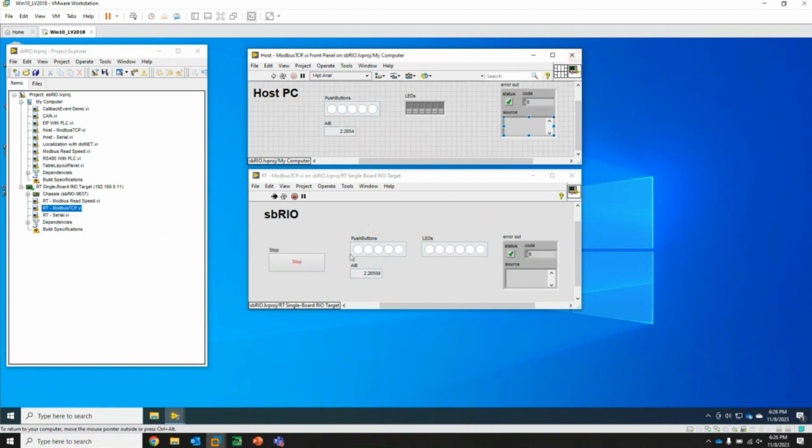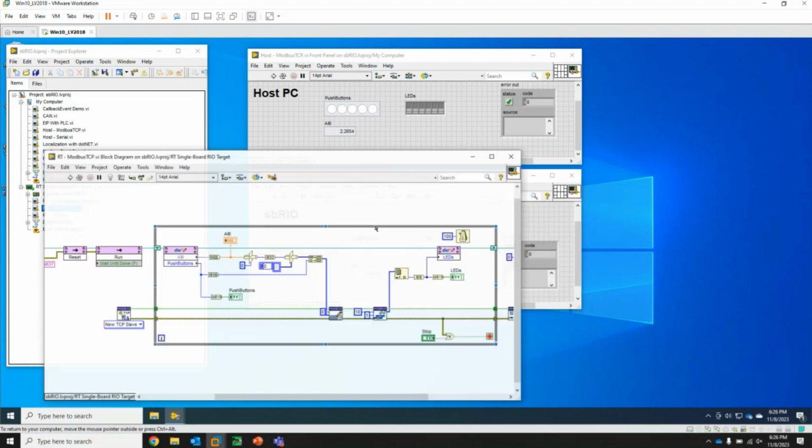I know this is for communicating with PLCs, but if you do have a simple real-time application and you're not trying to exchange too much, definitely use network streams or something else if you're pushing a whole bunch of data. But if you're just trying to get some discrete I/O, this is pretty simple to implement, and it's already a proven communication protocol.